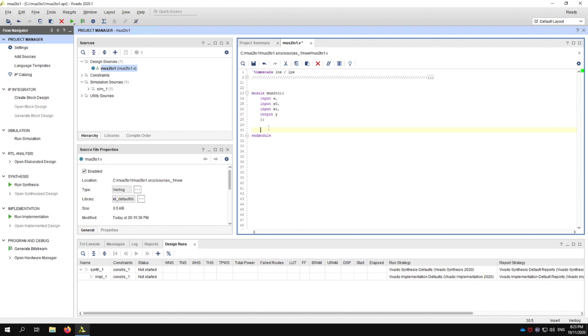Okay, so I am going to make a comment here, and I'm going to write down our Boolean expression. Recall that this is the functionality that I want to implement: y is going to be equal to s bar x0 or s x1. And there are so many ways to do this in Verilog. So I'm going to show you first one gate level way.